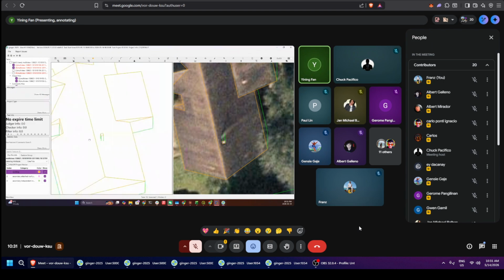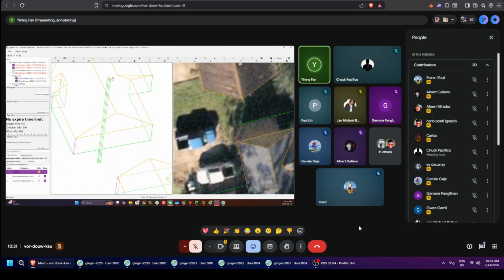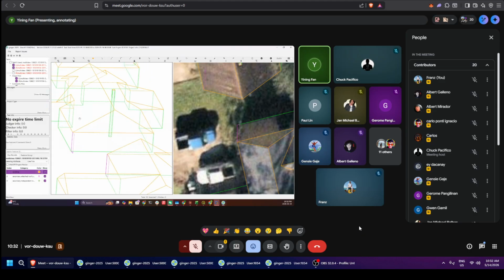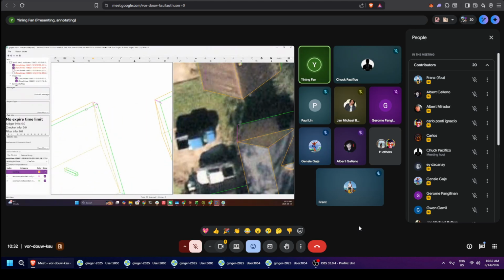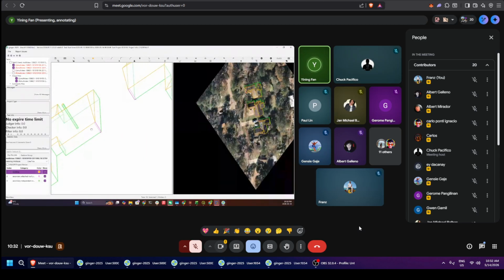At this side, the typical thing is that you want all the structure to have the same bottom. So first select this structure here, the chimney. Now hover over the wall, the structure you want them to have the same bottom with, and press 6. Eventually they will share the same bottom. Right here at the bottom you will see it gets colored, right?